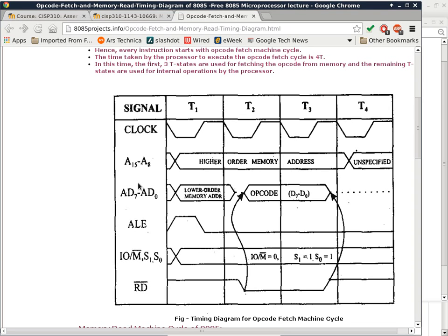Okay, and each via is a kind of cylindrical conductor. It's usually hollow, and you have to put those inserts into the holes that you drill on the motherboard. In other words, there's a lot of process just to make a circuit board these days. But why do you think they have to go to such length to make a 6-layer circuit board for modern computers?